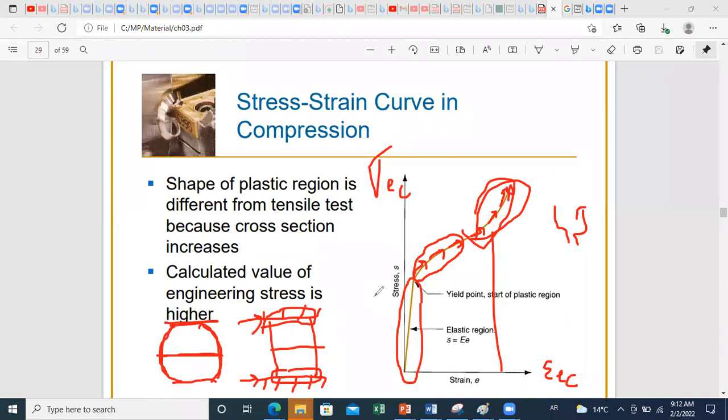For other materials, the nature of the principal failure mode can change from axial splitting. So you might observe splitting along the axis of your specimen, or you can observe shearing along a single plane. In other materials, you can observe multiple fracturing within the material. Okay, so you have a lot of sources that can lead to the limit of the compression test.